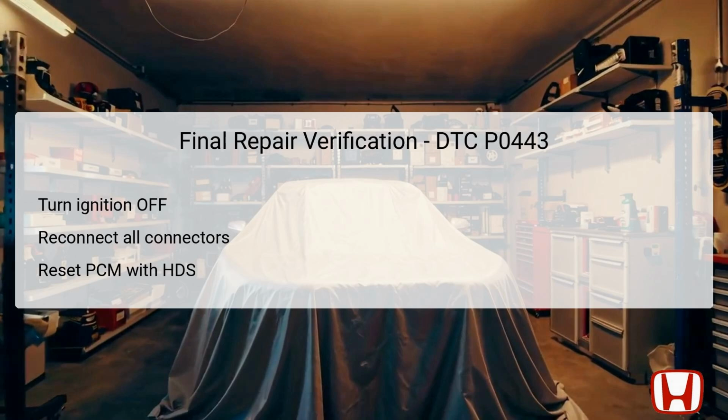After conducting all necessary repairs, it is essential to verify that the work has resolved the DTC P0443 issue effectively. Start by turning the ignition switch to the lock position to set up for connectivity checks. Reconnect all previously disconnected connectors, ensuring they are secure and completely seated to prevent future issues. Once all connections are restored, turn the ignition switch back to the on position.